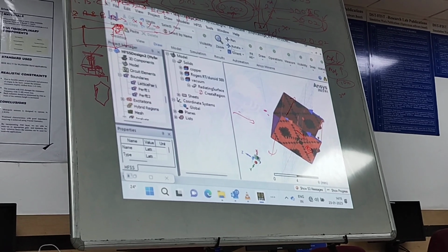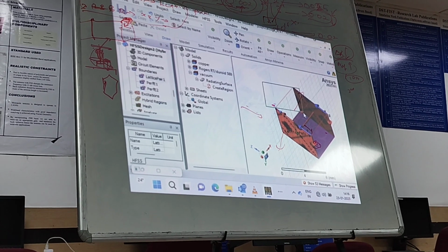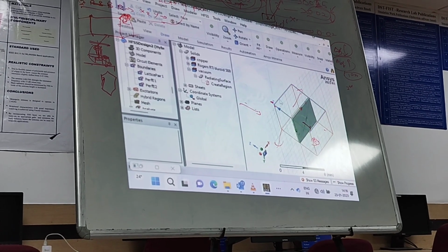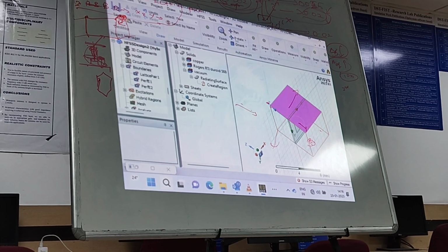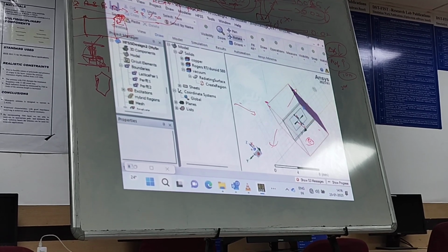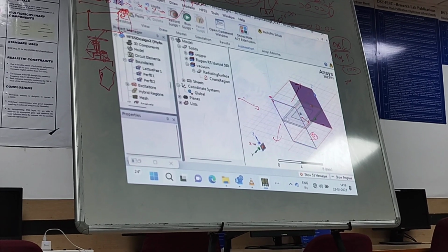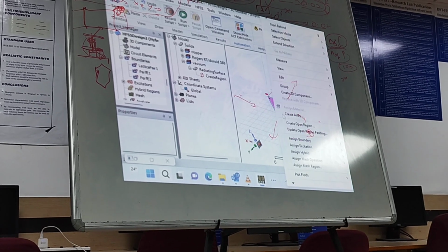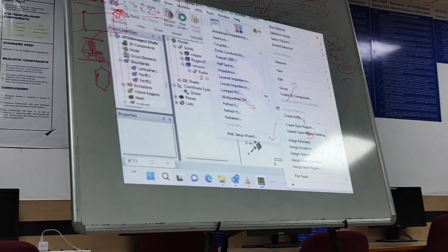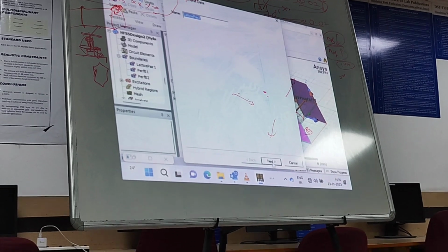So along the X phase we had assigned phi and theta, in which particular angle for 5G beam forming we will be getting it. The same way we will be assigning lattice pair along the Y axis now. Again right click, go to assign boundary, coupled and lattice pair here. So this will be lattice pair 2.